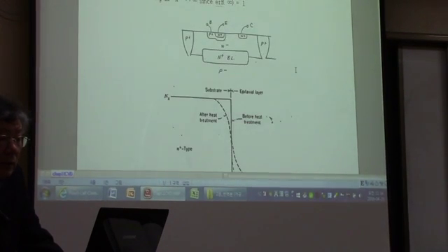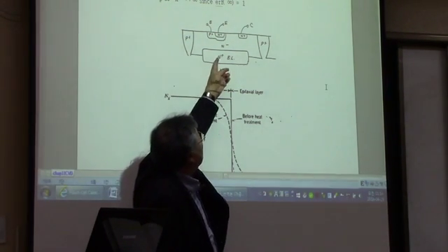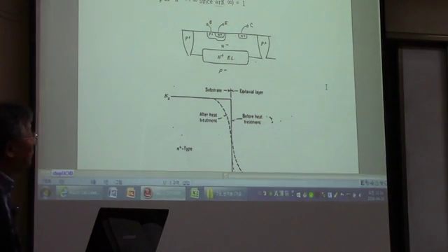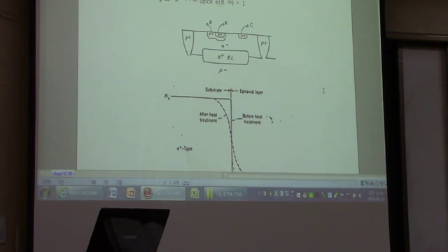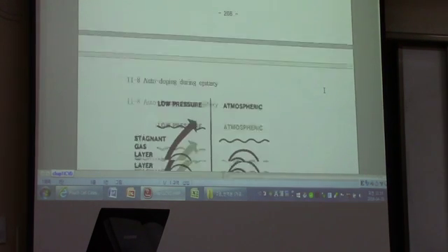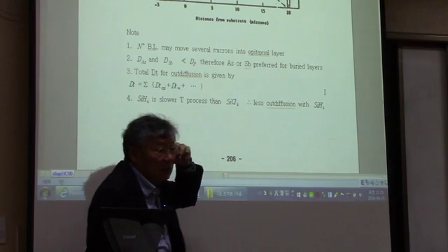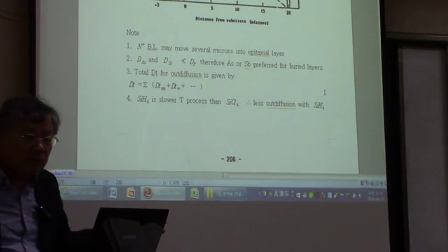All right. So in this example, where the buried layer is N-type, and the collector of the bipolar is also N-type, the out diffusion from the buried layer is going to be added to the dopant concentration in the base, okay, in this particular example. And people use antimony as the buried layer because the out diffusion of antimony is the slowest, because of the vapor pressure and so forth, okay.